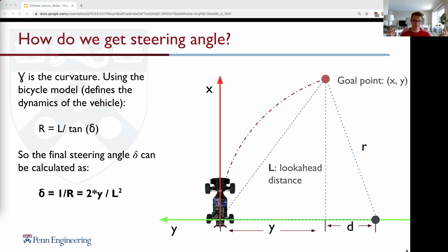And yeah, folks, that's all we need, which means now we only have to find out the next point. If we know the next point, we get the y coordinate, and the look-ahead distance is something we defined previously. This is our fixed parameter, and now we have the possibility to create the steering angle. That means if we have one point, we create a steering angle, we steer towards this point, then we get the next point and we calculate the next steering angle. And that's all we need, and now we can follow the race line.